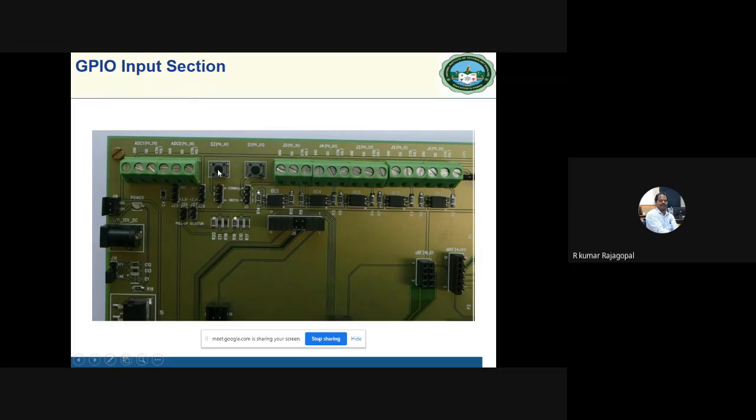Assume this is a switch instead of a sensor, but it is integrated with the processor in the form of an interrupt. The corresponding interrupt signal means rising or falling or both; usually either one or both are possible. For some applications it is the rising edge. When the rising edge occurs, the corresponding handler is automatically executed. In this particular case, we use it for transmitting a signal to the opposite node with the particular receiver address. That's what is available.